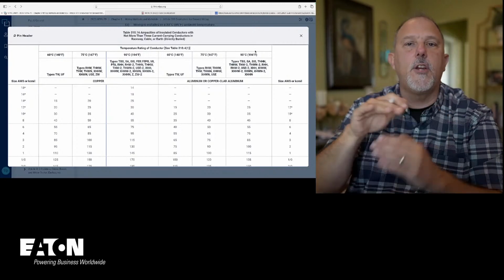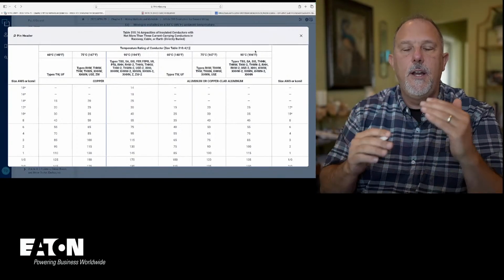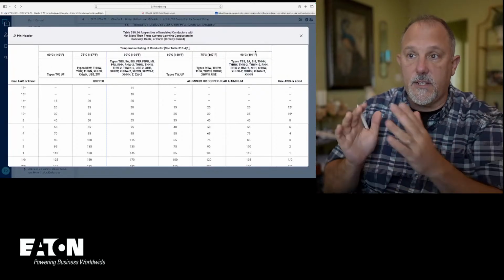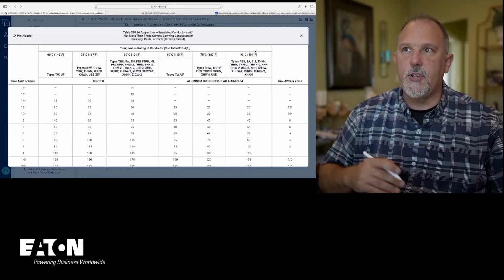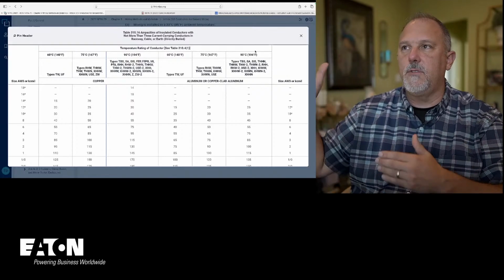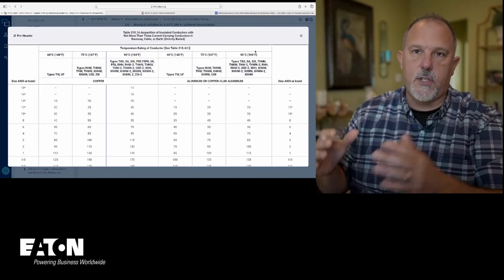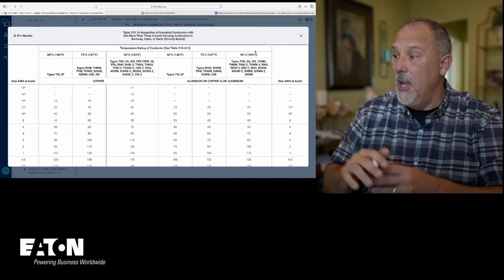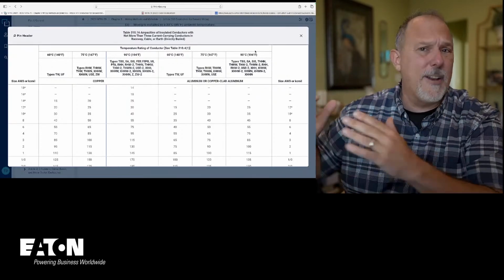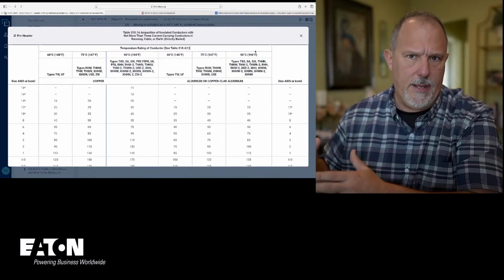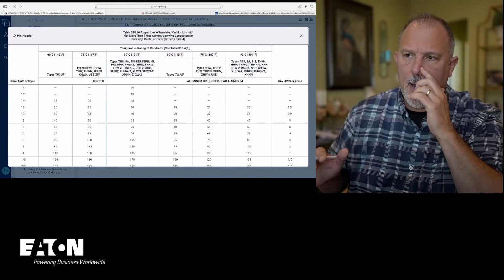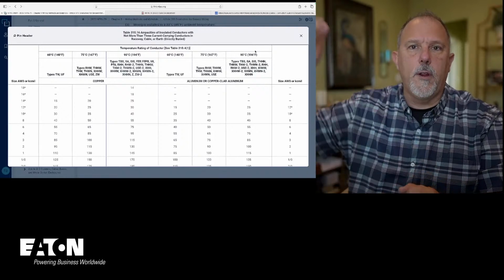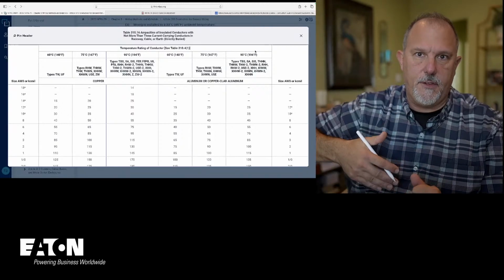conductor. I'm not going to go through the process of feeders like we do in Article 215, because this is a feeder, of calculating with and without temperature, calculating with and without conditions of use, and then determining which is the greater, because I'm already at 125% of full load amps. So I don't have to worry about that. I'm not working off of full load amps. I'm working down from the overcurrent protective device.